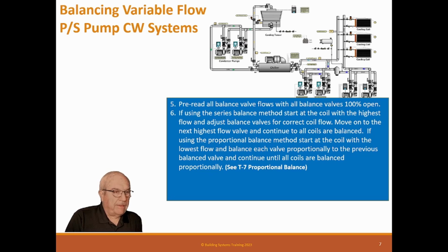Now, remember, as you go, when you get to a valve, and you notice the last valve was at 78%, and you start balancing this one down to 78%, that existing valve is no longer 78%. It may now be 79%. Well, you're trying to get it to its current position with this one balanced. So you have to go back and forth just a little bit with those two valves till you get them near the same. Then you go to the next one and do the same thing.